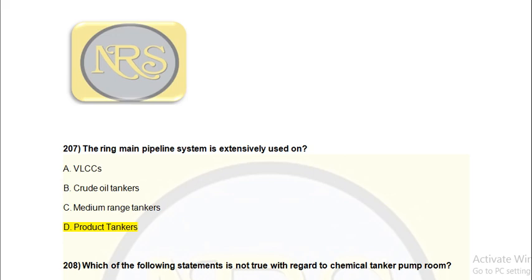That is, if we can carry one tank petrol, another tank diesel oil, another tank palm oil or high speed diesel, different cargo you can carry, and the effect of intermixing of the cargo is not so high. So palm oil we cannot carry in this, so we can carry high speed diesel, petroleum, and normal general petroleum compound, unleaded compound, like that we can carry. So a particular tank can be pumped out either by direct suction line or through another line by using crossover.